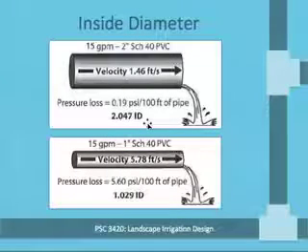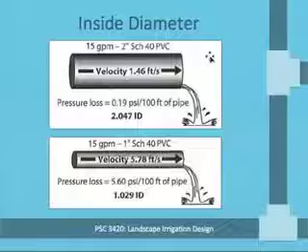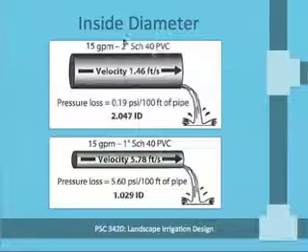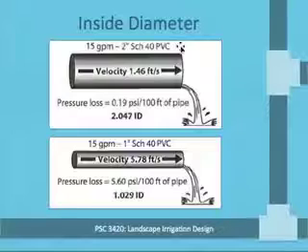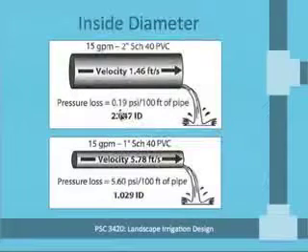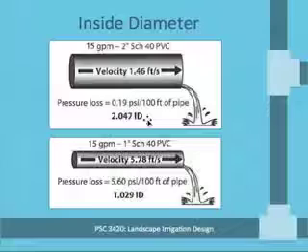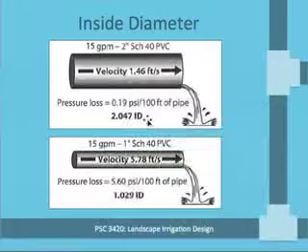When you're purchasing this pipe and looking in catalogs, it's also often going to be labeled just 2-inch Schedule 40 PVC. But that 2-inch is the nominal size of the pipe, meaning it's just for identification purposes or naming purposes. The actual ID, or inside diameter, of this pipe is 2.047 inches.